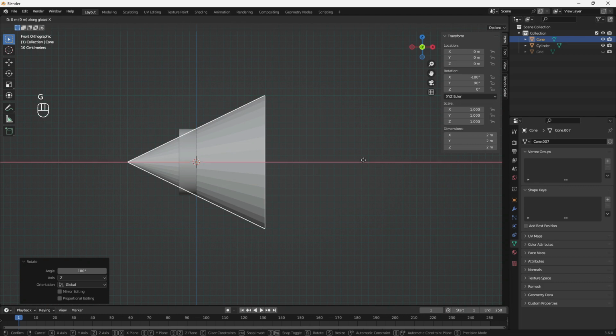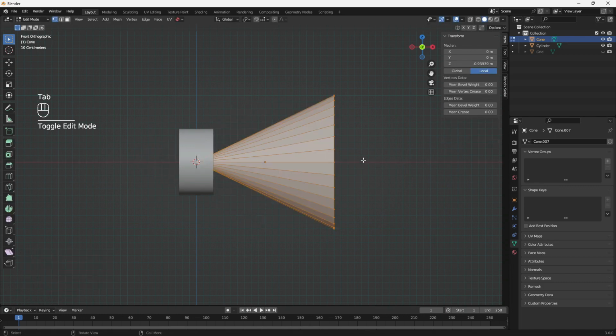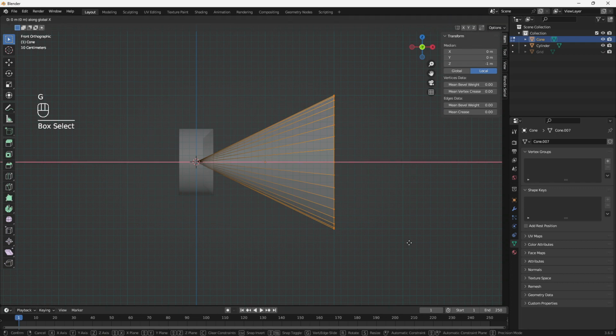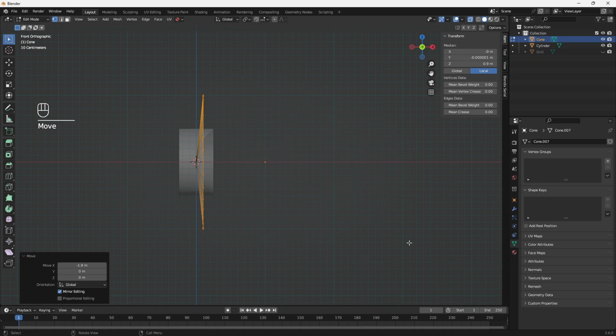To animate the sensor data in Blender, I'm using a cone mesh object with a wireframe modifier. For actions and operators, I have enabled the screencast keys, so you can easily follow the steps along with me. You can also watch the operators box to see the values I am using.